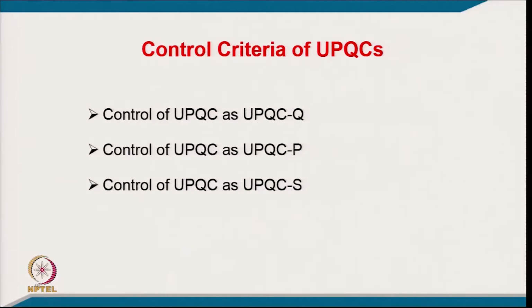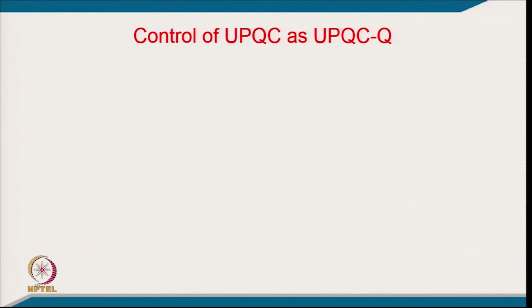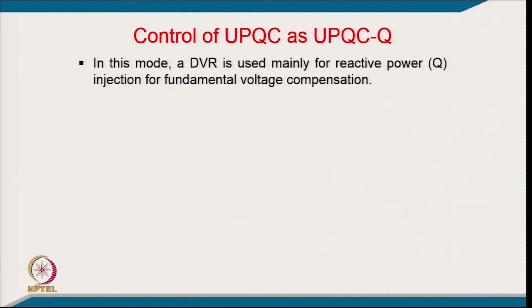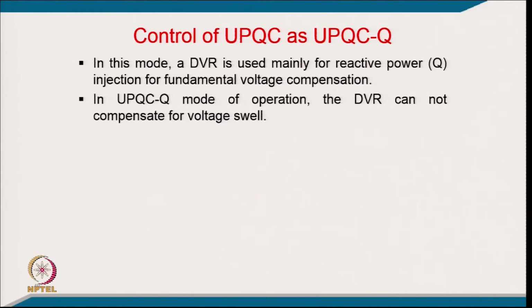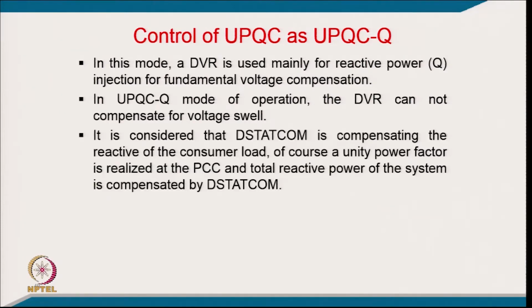Coming to control of UPQC as a UPQC-Q, or control of UPQC as a UPQC-P, which we discussed in the previous lecture, and control of UPQC-S. Coming to UPQC-Q, in this mode a DVR is used mainly for reactive power injection for fundamental voltage compensation. In UPQC mode of operation, the DVR cannot compensate for voltage swell, and it is considered that the D-STATCOM is compensating the reactive power of this consumer load.